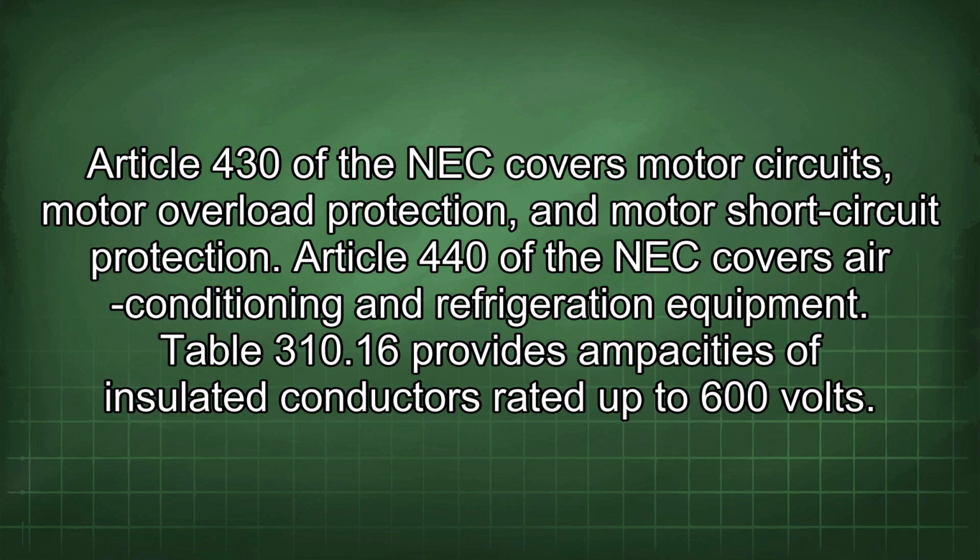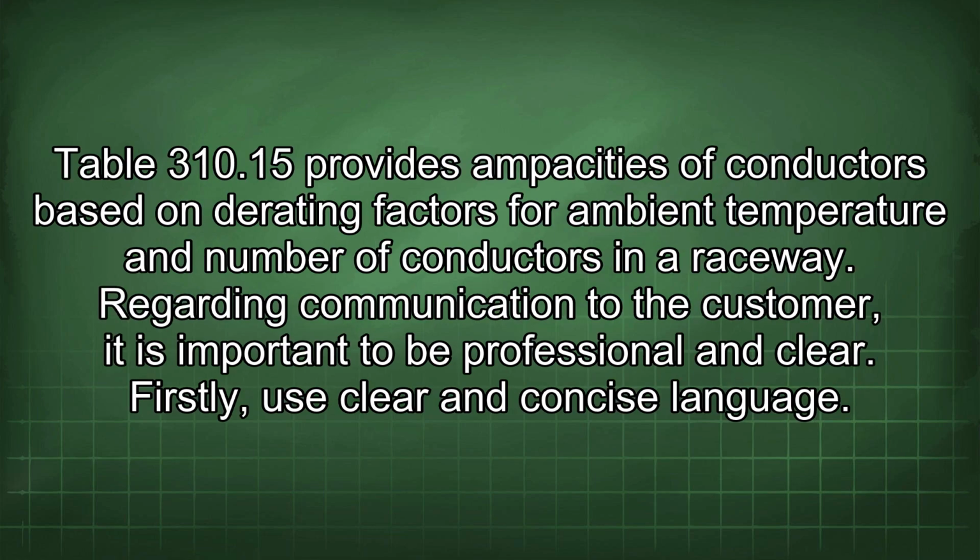Table 310.16 provides ampacities of insulated conductors rated up to 600 volts. Table 310.15 provides ampacities of conductors based on derating factors for ambient temperature and number of conductors in a raceway.